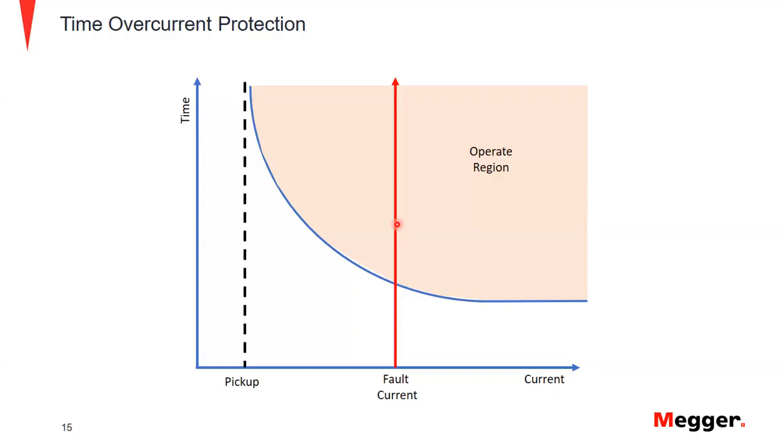The operations usually happen right on the line, with the plus or minus percentage listed by the relay manufacturer as well. If we were to try to capture this time here, as we're testing, we will provide specific current multiples along this graph to allow us to see the difference in time. As you can see, the least amount of current will provide us a longer time, and the higher amount of current will provide a shorter amount of time, which makes it an inverse style curve.